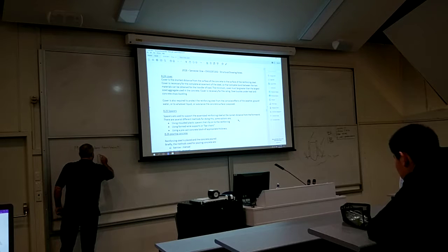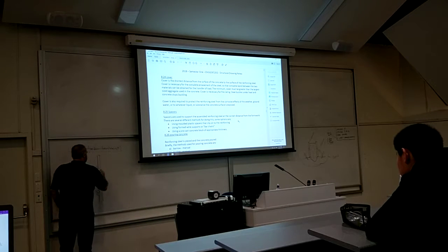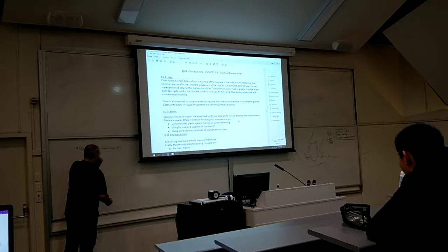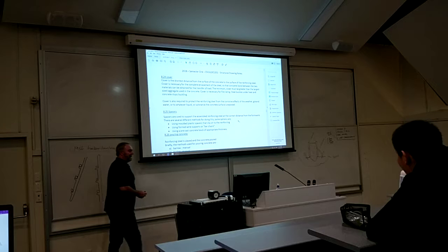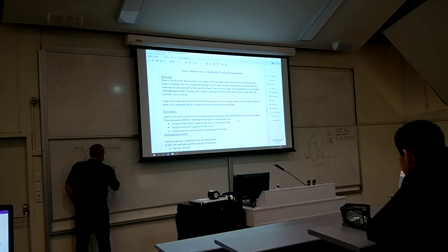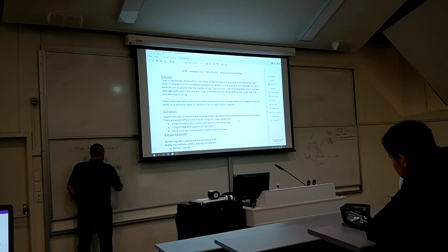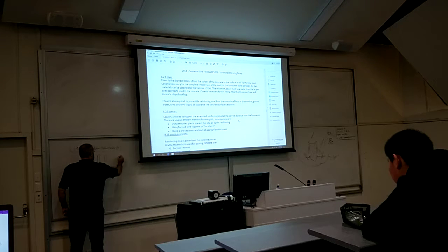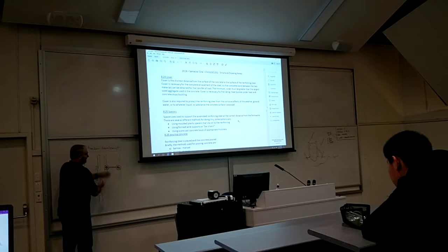And they'll tie the reinforcing, there'll be plastic bar chairs which they'll tie the reinforcing to as well. The other thing that they often have is spacers, which in plan view they sort of look like this. The reinforcing bar will sit at the same distance. You might have bars coming along in this direction. You can also have spacers in the other direction as well.